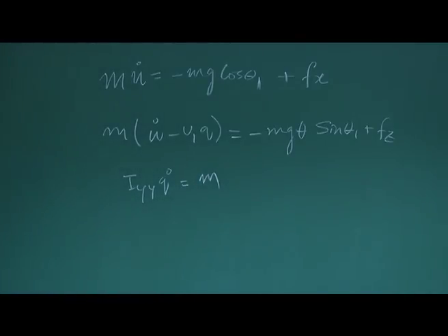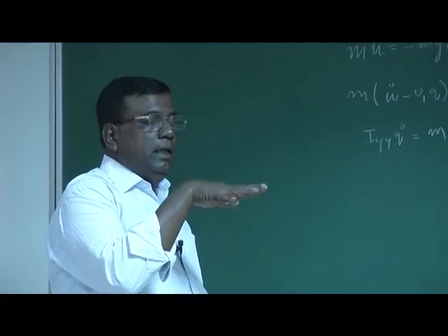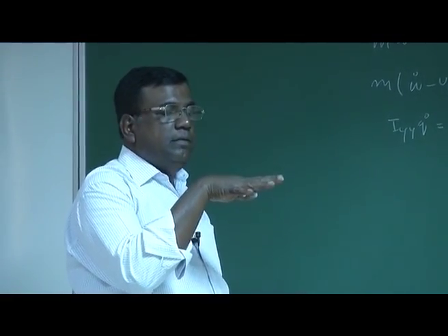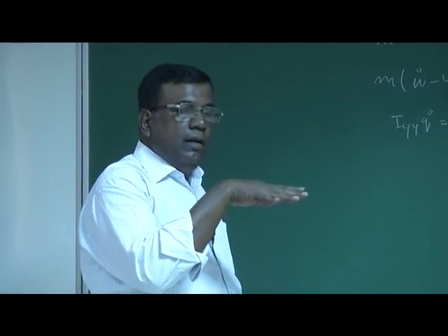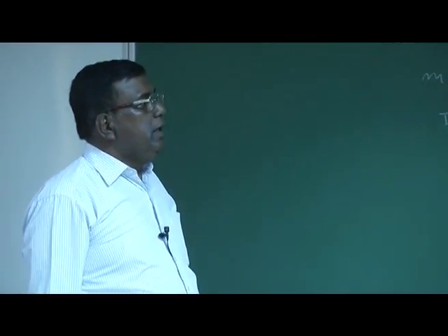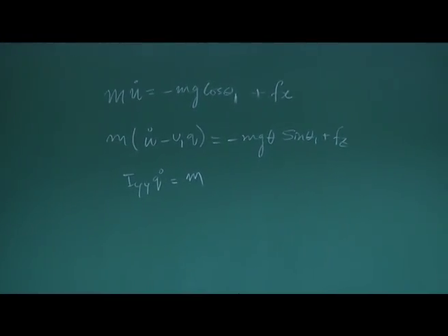And what are these Fx, Fz, M? They are the perturbed aerodynamic forces Fx, Fz, and the perturbed aerodynamic moment M. How do they generate? Suppose the airplane is at steady state, let's say cruise is our case. Then if I give a small disturbance, naturally it will have pitching motion, there will be a change in the velocity. So accordingly, the moment as well as the forces along the x and z directions will change, and these are the perturbed moment and forces.